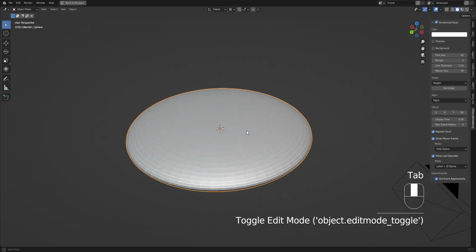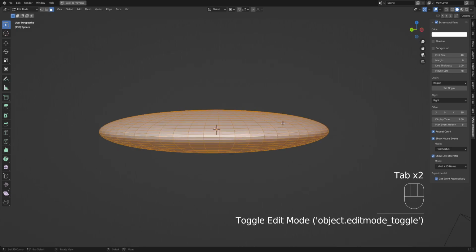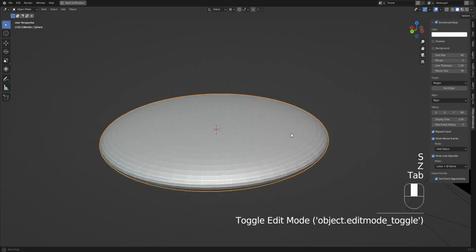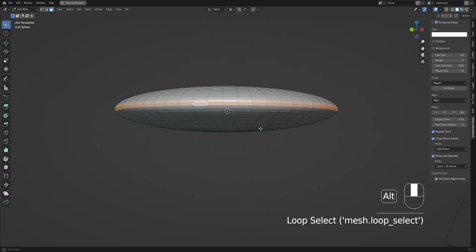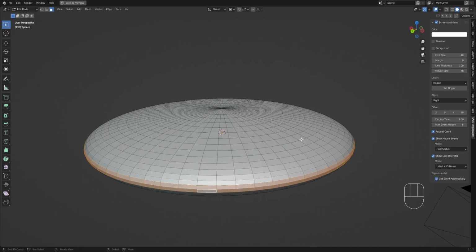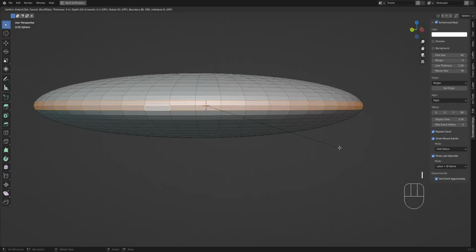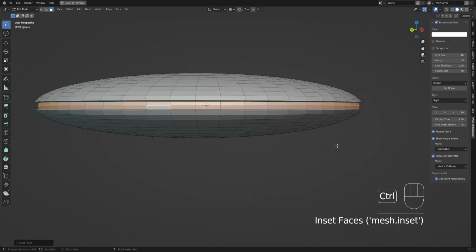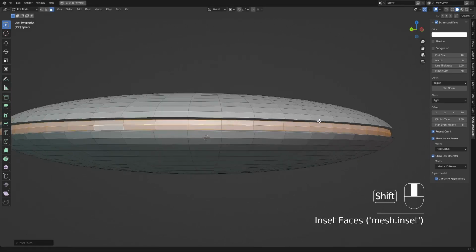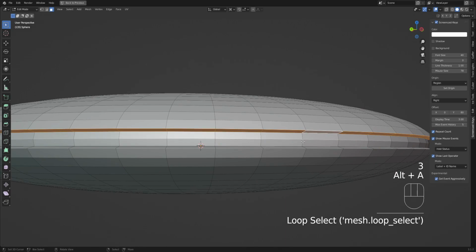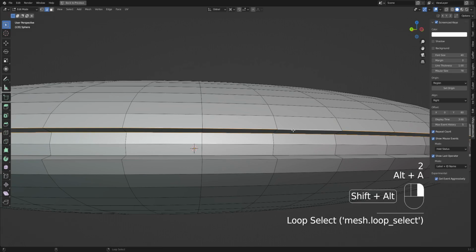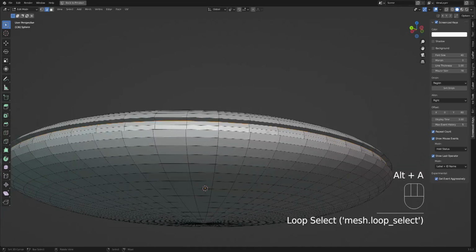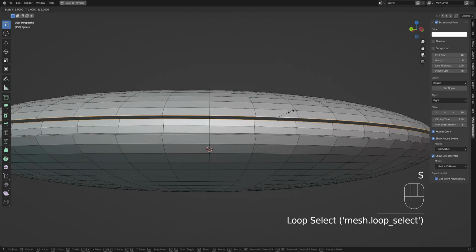So this is to emulate the saucer shape. You can design this yourself and create another design variation. If you wish to copy mine, go ahead. Scale on the z-axis, following the active element. So this edge loop here will scale to this edge loop here.